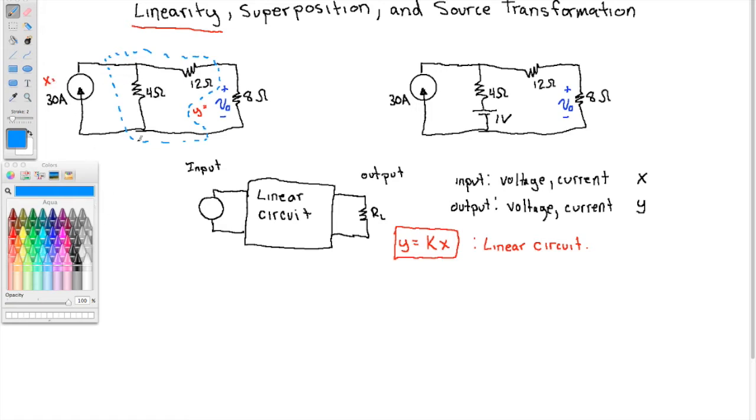So let's start to analyze this circuit. I'm going to use mesh analysis here. You can't forget about these things that we spent so long learning. I've got 2 meshes, I1, but I1 is 30 amps. So I've got 30 amps circling around there, and we'll call this I2.